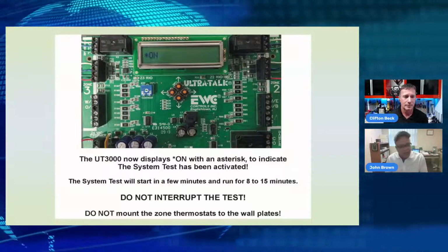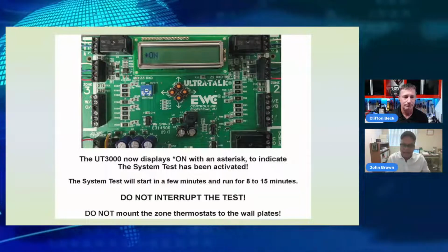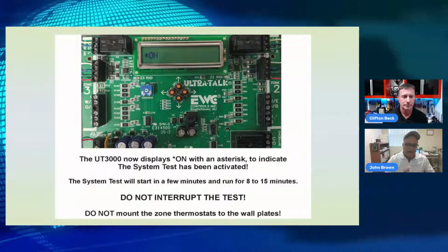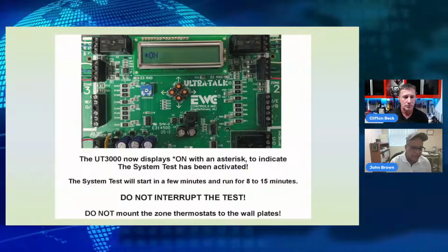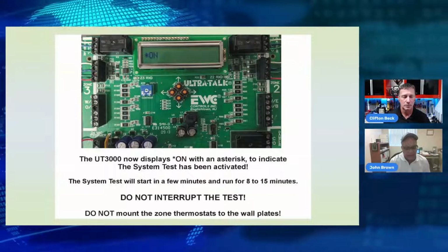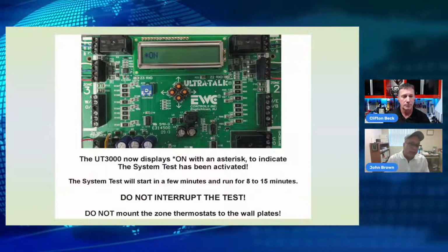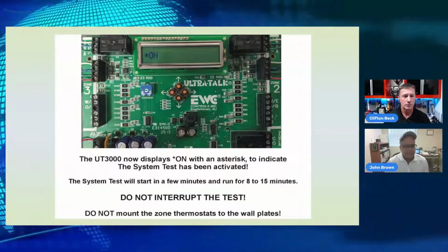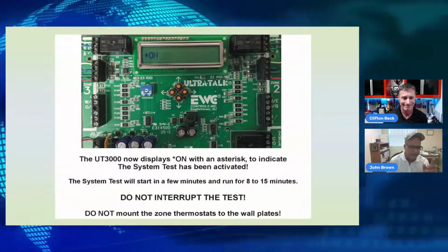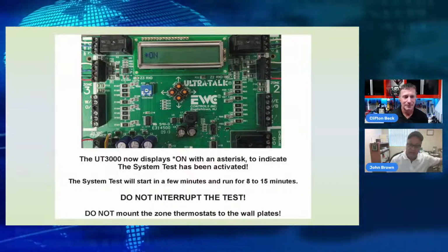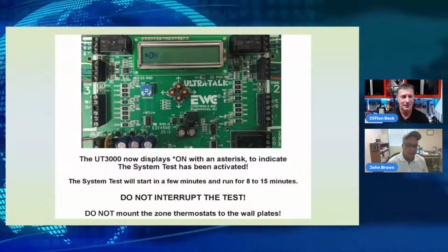Remember, when the network is not stable, everything's moving slower. You might have bad data packets, and bad data packets get thrown away, and then they have to be renewed and refreshed. So a long system test is an indication that there could be an unstable network. It could also be an indication that you did not put in a proper oil trap. The initial charge may not be correct. Remember, I think there's enough refrigerant for 25 feet of pipe. If I had much more than that, unless it's a horizontal coil, then it's slightly different, but not much. So that's a good point.